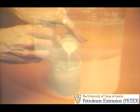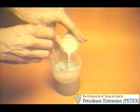Well, the answer is that attapulgite builds viscosity by a shearing action. The attapulgite particles must be stirred vigorously into the salt water so that the particles will stick together and form a structure like a brush heap or haystack.